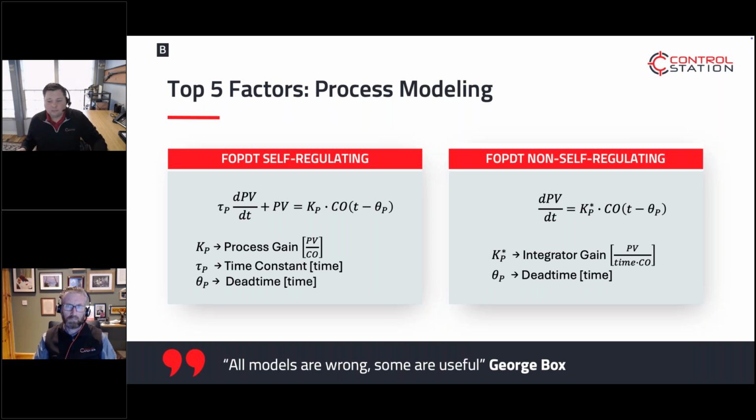All right, generating these models is key. These models are what allow us to generate tuning parameters and understand the behavior of the system. If we're doing MPC or APC, we can use these. If we're doing things like dead time compensators, we can start to use these models in those equations. And so they become very, very important for us to understand those dynamics.